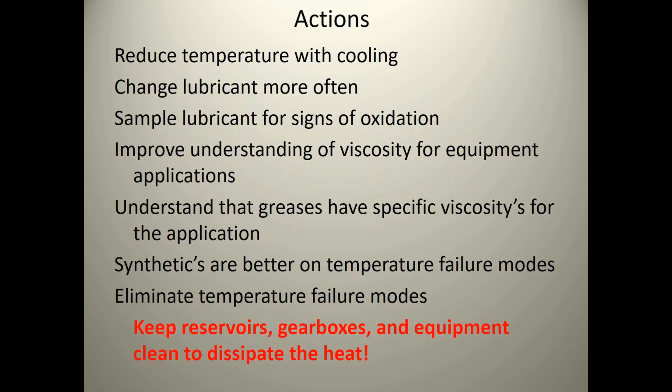So what do we do with some of these failure modes of our lubricant? Well, we have to find some ways to cool it. If it's in a hot area where it's affected by temperature, are there some ways we can cool? A lot of times it's just keeping the component, like the hydraulic unit or the gearbox, clean so that dirt's not an insulator. Sometimes we may have to put some air cooling coils on there.